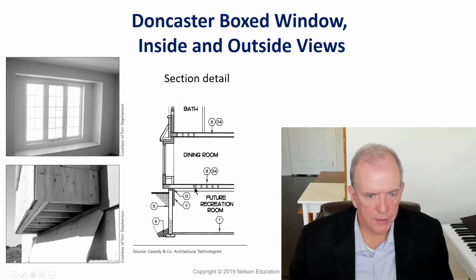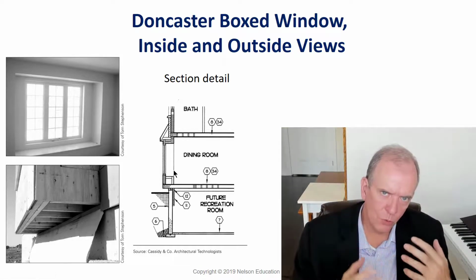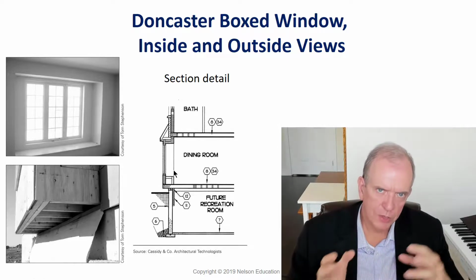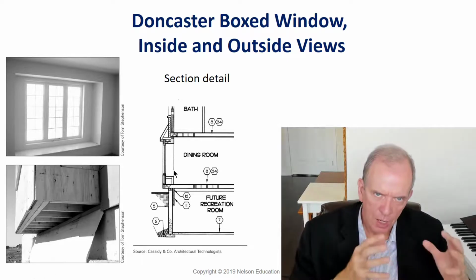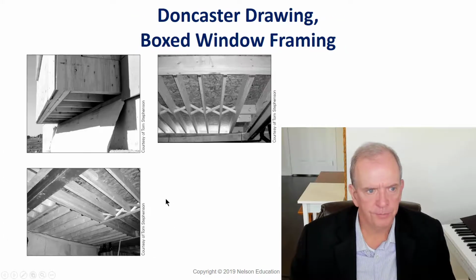And this is the joists that are sticking out this way, and they're tripled up. So you're always trying to visualize how these framing members are going together from the drawings to the actual construction of a residential structure. So it's really worthwhile to spend a lot of time trying to interpret and understand drawings.